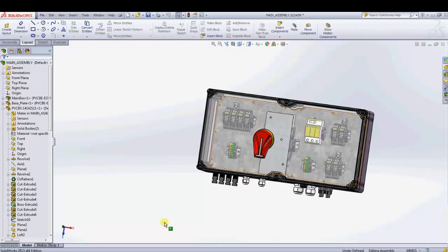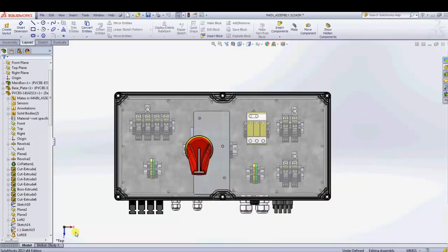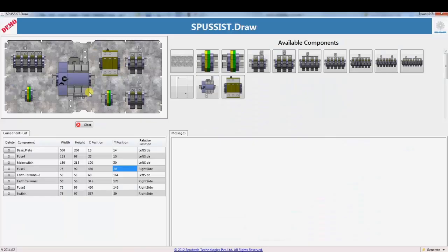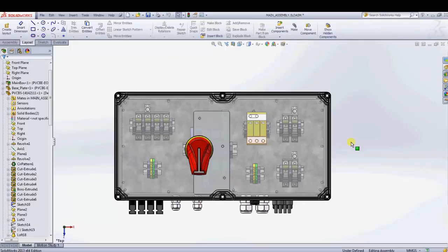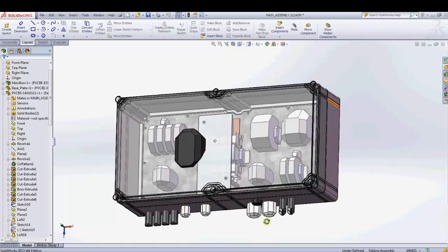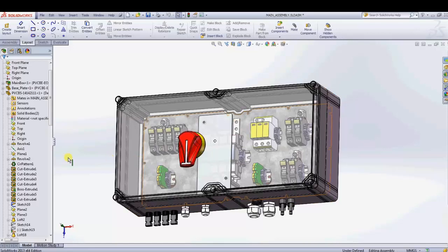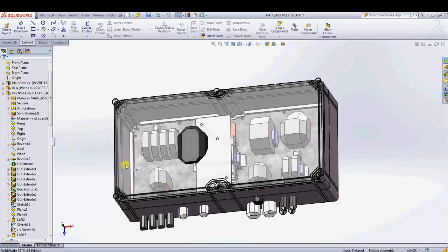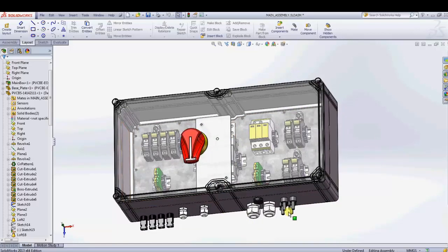If you notice, the 3D model will be generated exactly the way you've created your design over here. Whatever you place here and wherever you place it will come out as a 3D model automatically. Another advantage of the system is that it also automatically generates the 30 mm gap that each fuse goes in case there are 2 layers, and 90 mm in case of 3 layers.